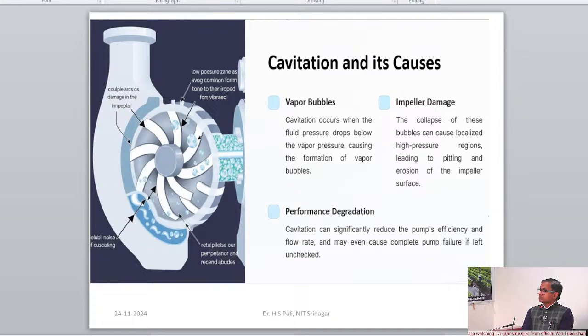But if we use the 5.5-inch impeller, then we would get around 22.5 feet of head. In some instances, our required flow rate and head pressure might fall between the two impeller diameter lines. In such cases, we can often machine the impeller down to the required size to get a better match.